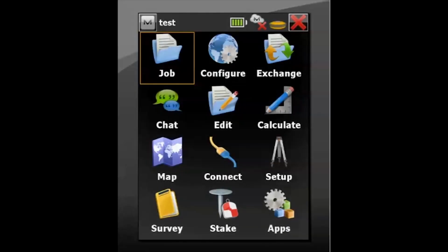This video shows the process of creating a localization for a GPS job on site, i.e. if you're not working on a national grid coordinate system, or if your site coordinate systems are a pseudo national grid or based on a simple 1000, 2100 origin point, for example.